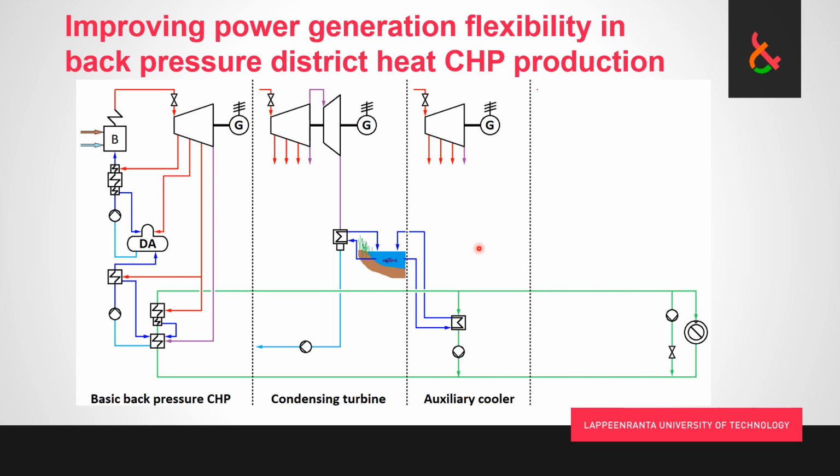So it's an easy, simple and cheap way of adding a lot more flexibility that we usually want to have it. Now, the drawback is that we don't get quite as much additional power generation with this one, because we only add to the amount of steam flow through this part of the turbine, and here we would also additionally get additional expansion, and this we don't get here.